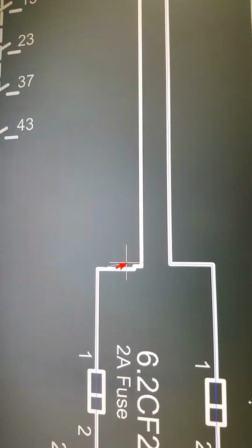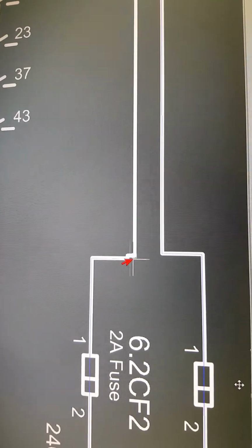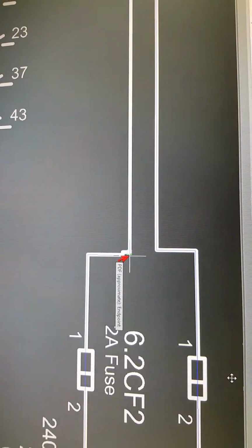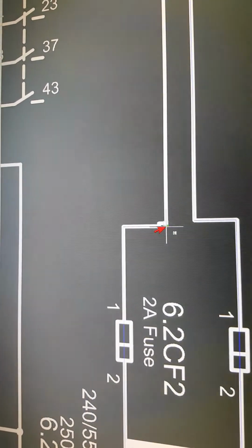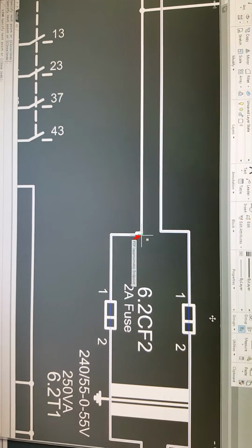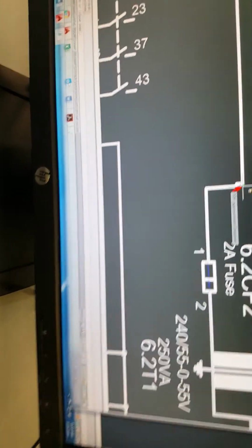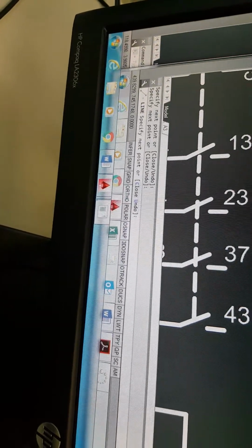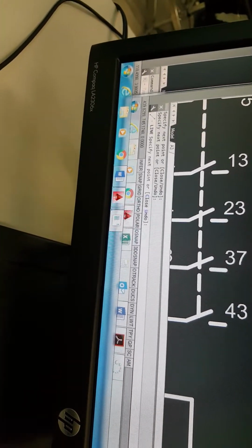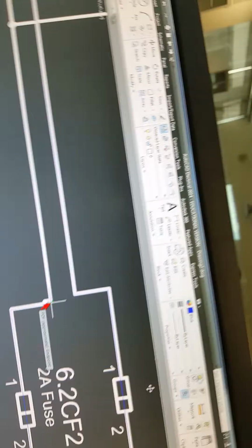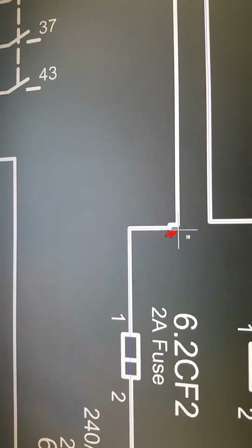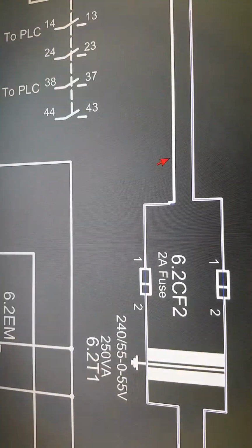Of course, here there's a little bit of an anomaly. You can work with it or you can make it the right angle, right? So if you hold the shift key, it temporarily turns on orthogonal. Look at the bottom of AutoCAD. See, the ortho has become blue. If I remove my finger from the shift key, it goes off. What's orthogonal? It makes sure that the line is either vertical or horizontal. So shift, I can put it in there, and then I can continue.